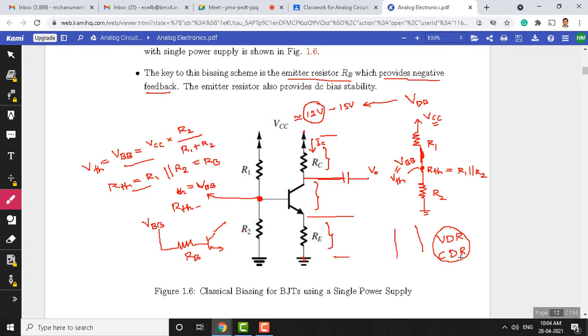Same thing we have done in this topic also. Similarly, you can also calculate R Thevenin. When you are calculating R Thevenin, the DC voltage must be grounded. Just remove the DC voltage which we considered while calculating Thevenin's voltage. Now let me write the original circuit here, resistor R1 here, and now I will ground this.